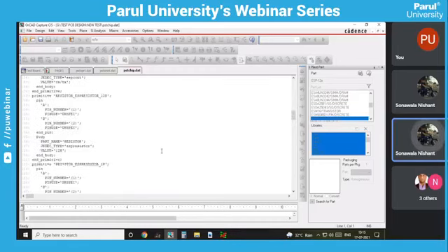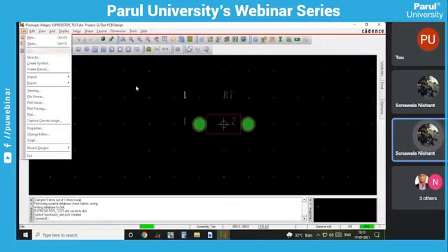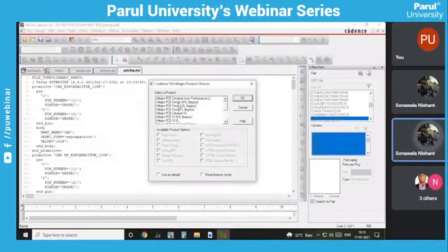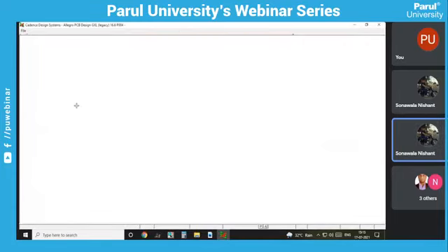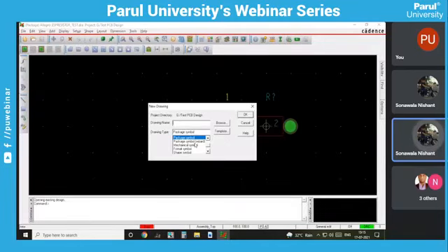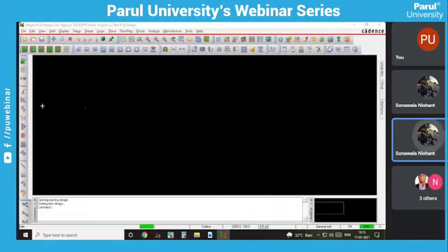Now let's design a board. To design a board, we have to go again into PCB Allegro. I'll start again and show you. Go to PCB Editor. Inside this PCB Editor, select the Allegro PCB Design GXL. Go to file, then select new. Now we are designing a board, so we select board and mention the board name. We are giving the board name as test ESP-PCB. Again, we got the blank page.